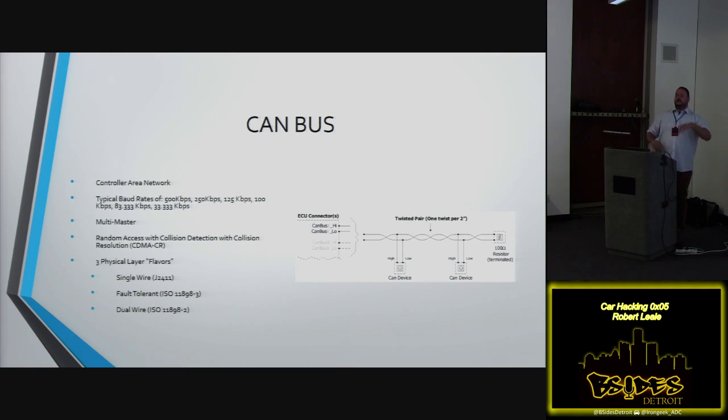But with efficiency, we lose that security, like we were talking about earlier. So if a CAN bus message is sent on the wire and you wanted to send your own version of that exact same message, it can be done. And that's the challenge with CAN bus. There are ways of mitigating that, and we've seen you can sign the message, but you only have 8 bytes. So your signature's got to be really small, right? Very small. 8 bits of signature. It's a challenge to really secure that, but you could. That's sort of what some OEMs have to do now, they put small signatures on them just so it's more challenging. But replaying them is still very much a possibility. But if you want to change it, it's a challenge.